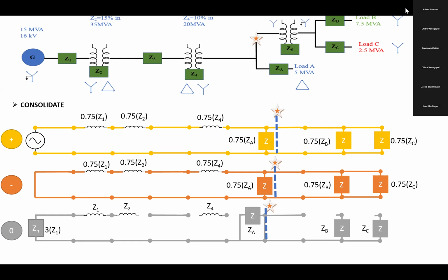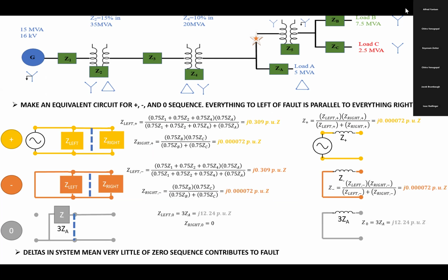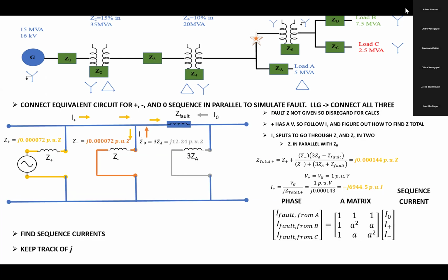And then line to ground fault. So that we have to remember: solve the zero sequence, positive sequence, negative sequence, and get the impedances. For a line to ground fault, all the impedances must be connected in parallel. So put all these impedances in parallel. Now get the values I0, I1, I2. Change them to IA, IB, IC, and then VA, VB, VC.